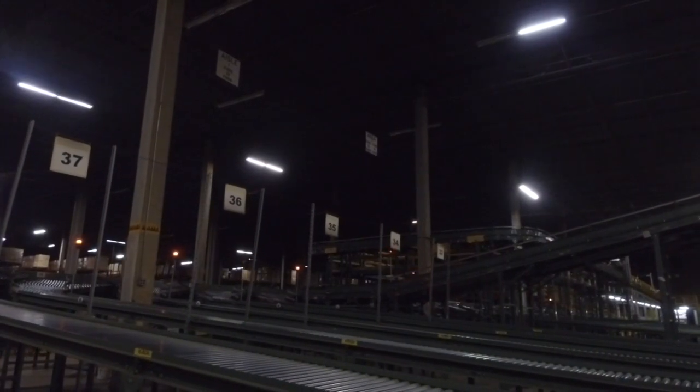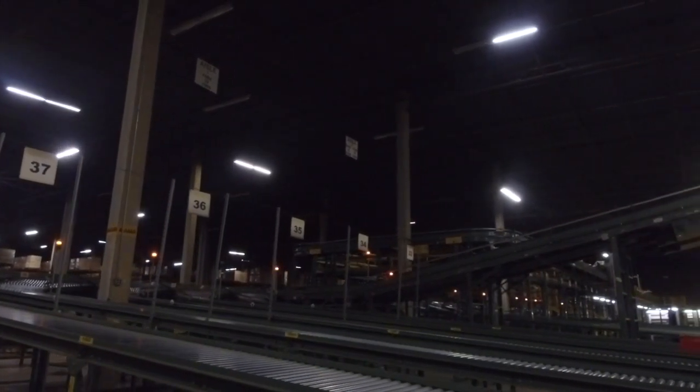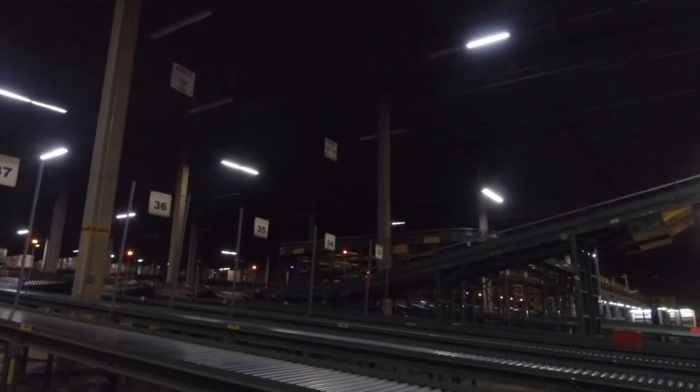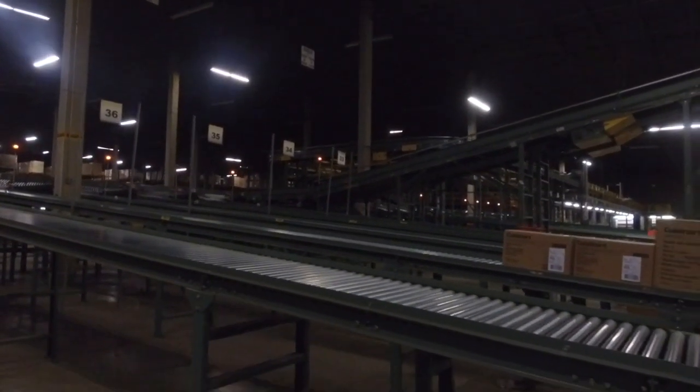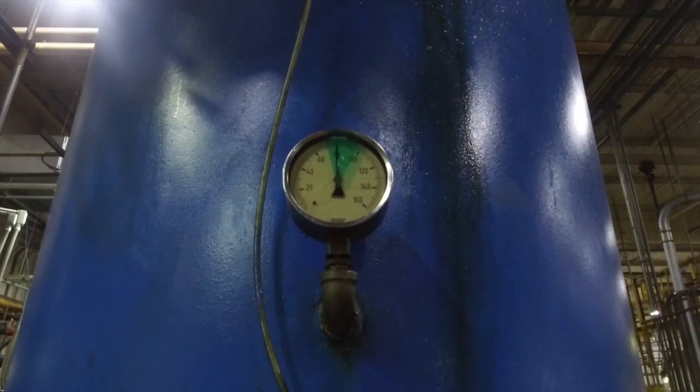You can also take advantage of times when the plant is in shutdown mode. Line pressure will drop over time due to leaks in the system, so even with the plant shut down, the compressor will continue to cycle on and off to maintain the pressure set point. This average cycle time gives you a good measure of the overall system's health.